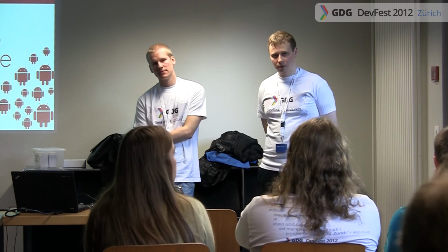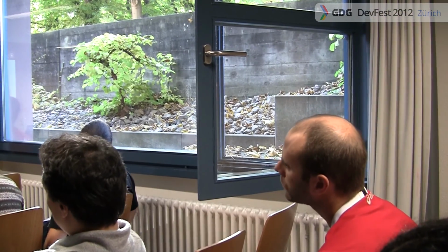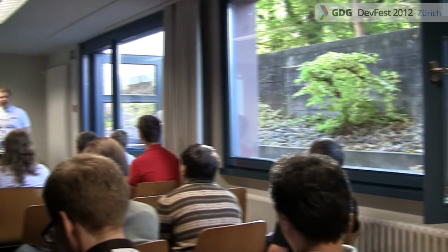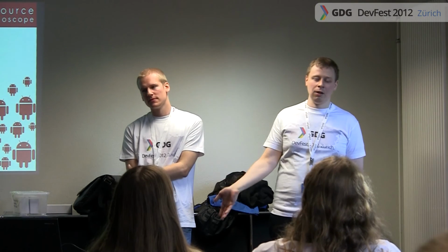Presumably, as it's a USB device, you could also plug it into a PC or... Exactly. Yeah. We already have a version that we use where we created some tool. Since every single device you see here gets a serial number from us, and we pre-calibrate it, we have an automated process where we wrote some Java code with JNI and libUSB, where we hook up the scope to the computer and collect data samples, and we output a sine wave on the function generator where we know exactly what amplitude it has, and we calculate the scaling factor, since every single hardware has a different scaling factor for each attenuation setting. And we do that already automated with libUSB on the Linux desktop.